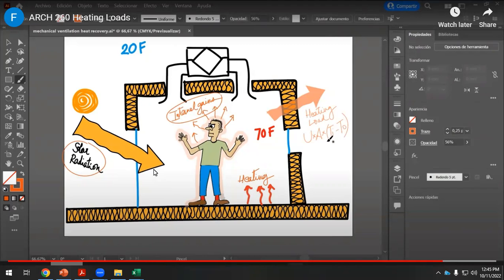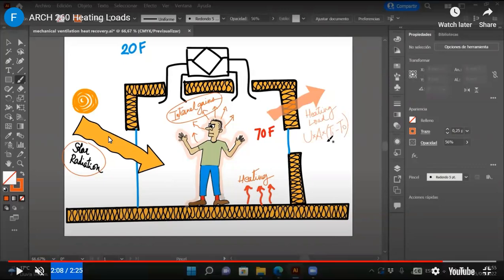We have not worked with the free solar gains that we can have in buildings. And that's important. It's important because there are some days in which our building can be a zero energy building without doing anything, without using PV panels or solar collectors or whatever. If the building is good enough, even if it's cold outside, but we have a sunny day, we can have a zero energy building because this big arrow is bigger than the arrows that are going out.